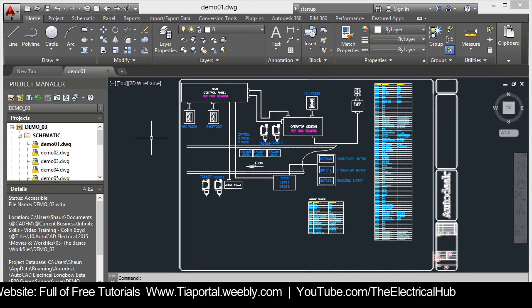Now, I might not want to open up new drawings that way just by selecting a template. I might want to utilize a slightly more sophisticated tool that's been around for a long time, and that's your startup dialog box. Now it's controlled by the startup variable. So make sure down on the status bar you've got your dynamic input on. Bring your crosshair into the drawing area and type startup, all one word. So there's startup there. You can press enter if you want to, or on the suggestion menu, just click on the word startup.